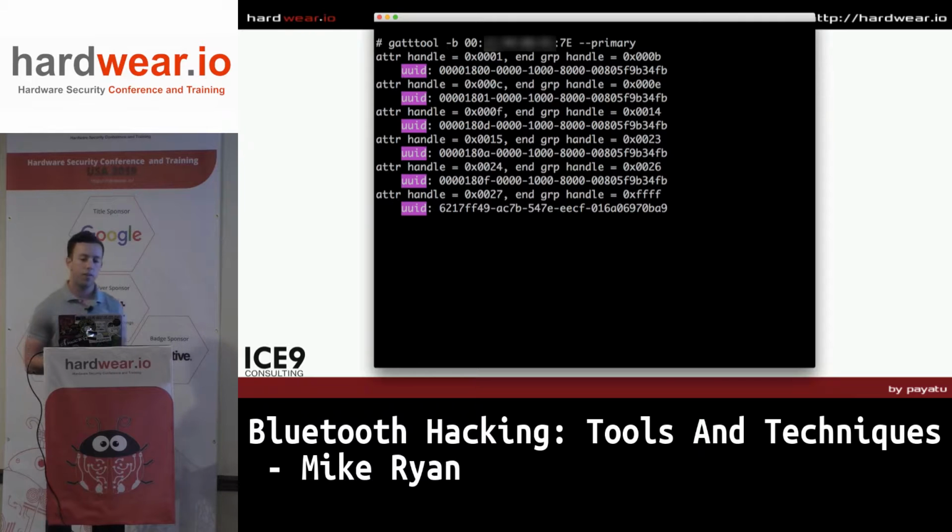This is only a 45-minute talk. I don't have a lot of time to dig into how to actually talk to these devices. I'm going to focus a little bit more on reverse engineering them. But if you want to talk to the device on Linux, I usually use Linux to do this because it has a really rich set of tools for talking to Bluetooth. The gatttool command is the one that I usually use. That's 3 T's in a row, gatttool. And this tool lets you do really basic rudimentary communication with Bluetooth.